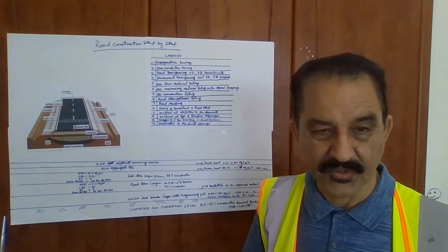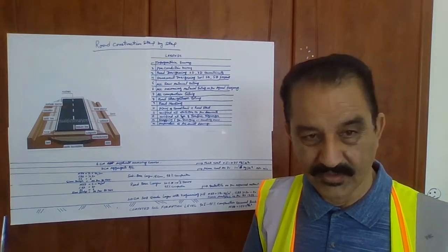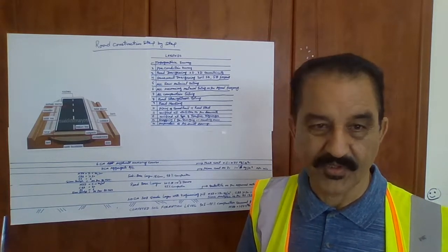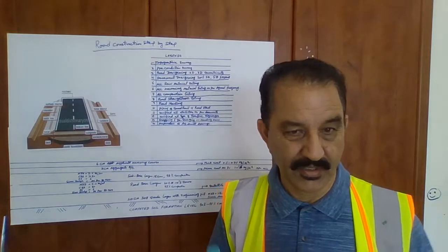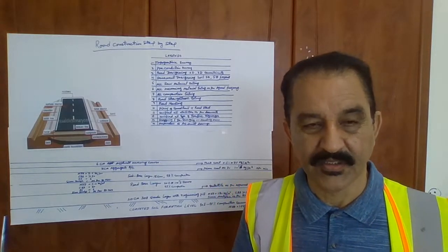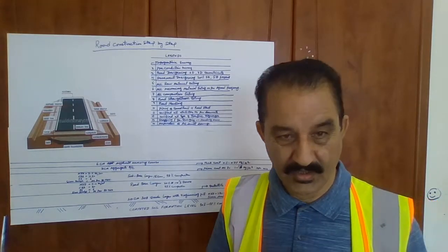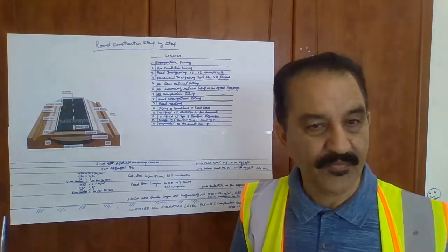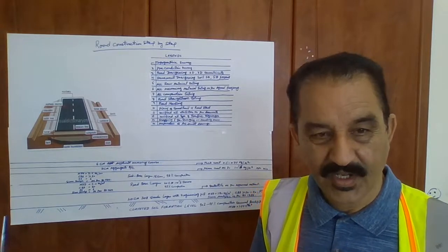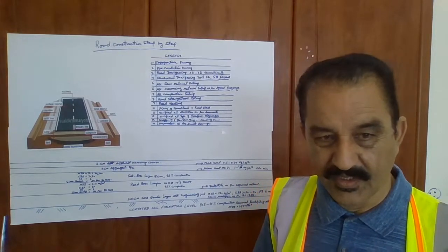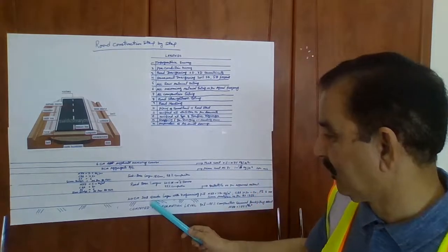Every 30 centimeters, 20 centimeters, whatever is agreed as per the specification, whichever limit is agreed, either 30 centimeters or 20 centimeters, it should be tested according to the agreed frequency, and definitely it will reach the subgrade level.